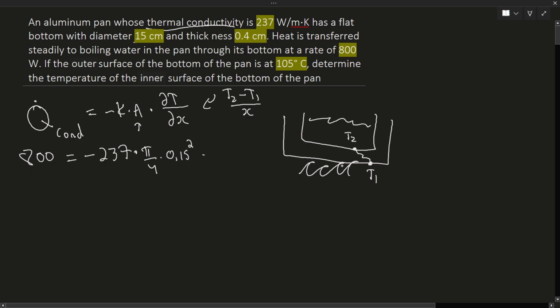So when you put your pan on the fire, the bottom is going to be T1. That's the first surface where the fire is touching. And then it's traveling all across the body of your pan up to T2, okay? So the X is going to be your thickness, which was 0.4 centimeters. That's it, okay? So all we have to do is plug in the equations.